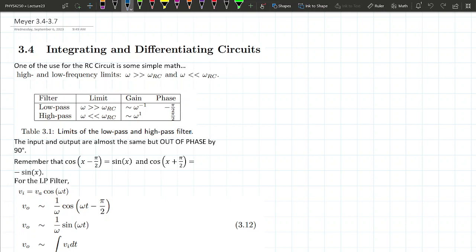And one of the key things that we learned in chapter 1 is this thing called the voltage divider, which has resistor 1, resistor 2, and whatever the output is in here, it's just the gain, which is actually R2 over R1 plus R2. We're going to use that technology over and over and over again, because a lot of times instead of resistance we end up with impedance, if we're dealing with capacitors and inductors.